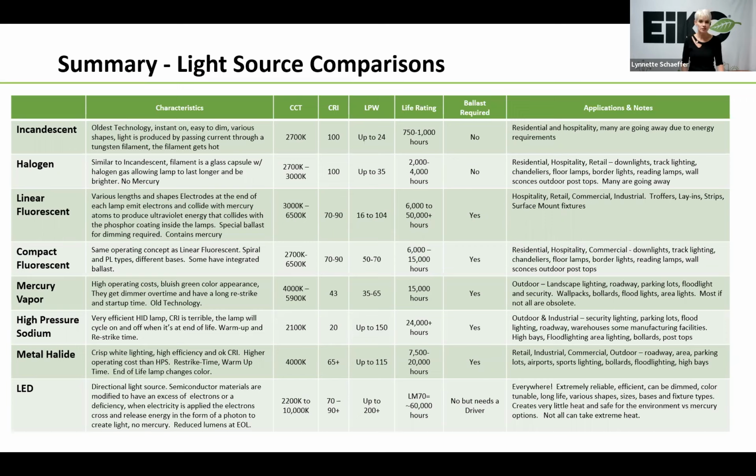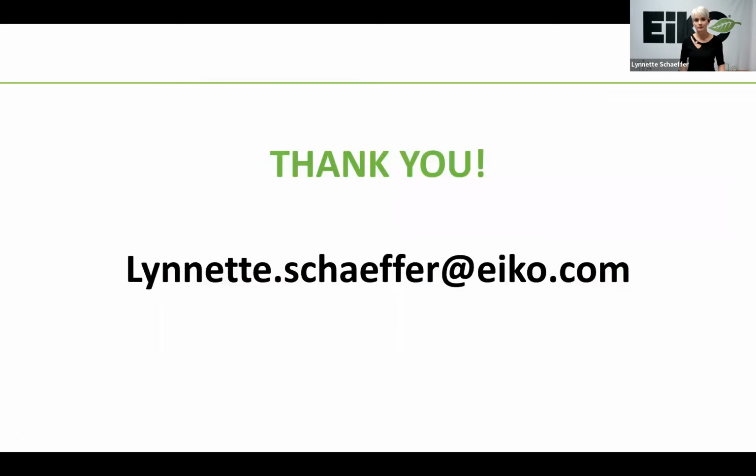Also, I don't believe I mentioned this, but most LEDs achieve about an 80 CRI. However, there are some energy codes that require the lamps or fixtures to achieve 90, such as California JA8, and you will learn about that in another training video.